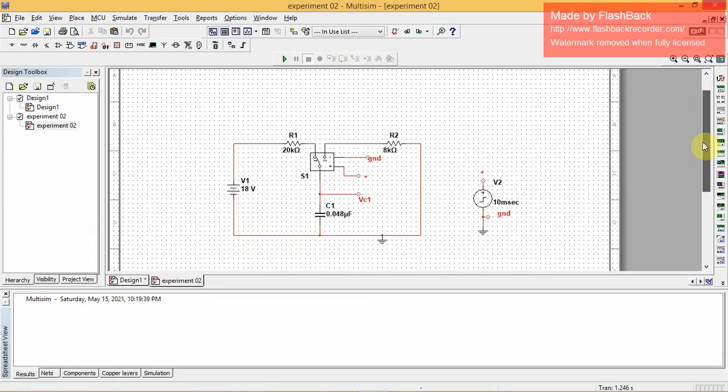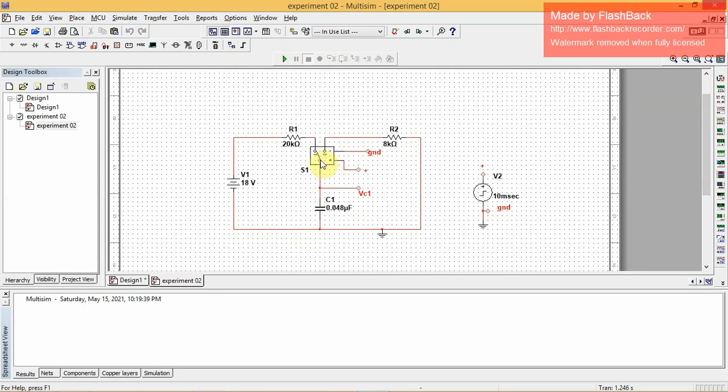There we go. Right, so in this circuit we have the same single pole double throw switch over here, a step voltage source, bunch of resistors. This is your charging resistor, and this is your discharging resistor, a voltage source. And these little dots over here are called on-page connectors. What these do is they allow me to connect this step voltage source to this single pole double throw switch without actually making a physical connection. So it's actually the same as taking this, putting it here and connecting it there.